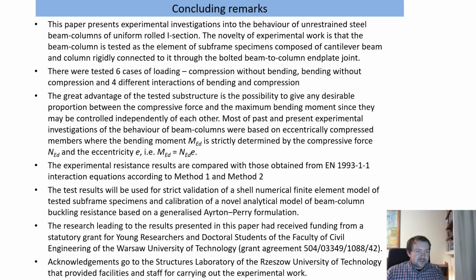The test results will be used for strict validation of a shell numerical finite element model of tested subframe specimens and calibration of a novel analytical model of beam column buckling resistance based on a generalized Ayrton-Perry formulation.